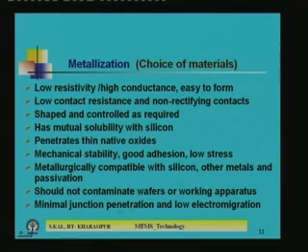Another is minimal junction penetration, that is very important if you go for shallow junction devices. Aluminum dissolves in silicon and goes into the deeper layer of the silicon, so it may short the shallow junction. If the junction depth is not very high, there is a possibility of shorting the junction. So, that also you have to take care of. That means, there are a lot of points which you have to take care of when you are selecting a certain metal for metallization. Okay.